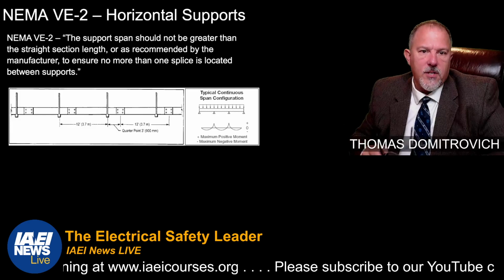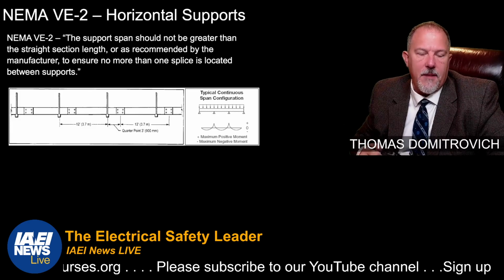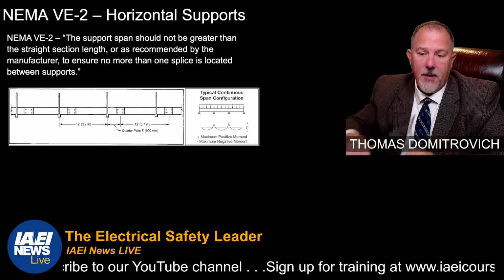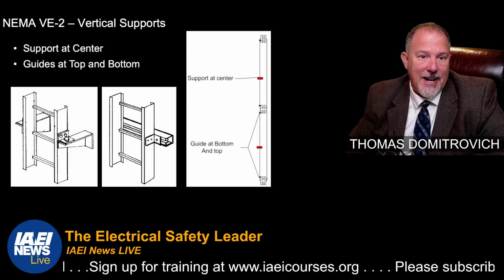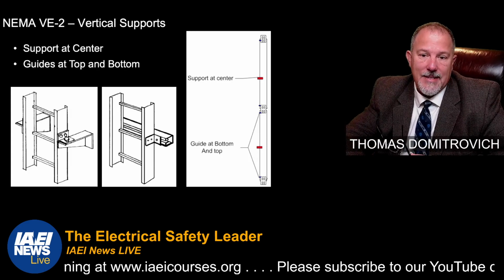Horizontal supports should not be greater than the straight section length or as recommended by the manufacturer. No more than one splice is located between supports. I believe we already covered that. Vertical supports, you want to support at center, guides at top and bottom. Support at the center.